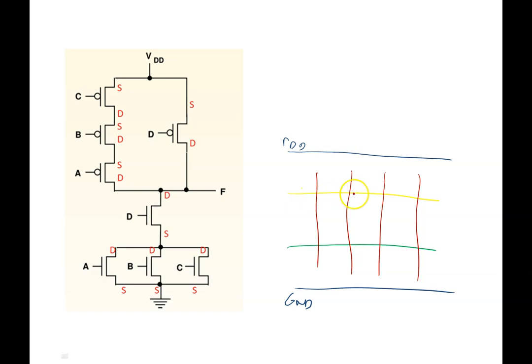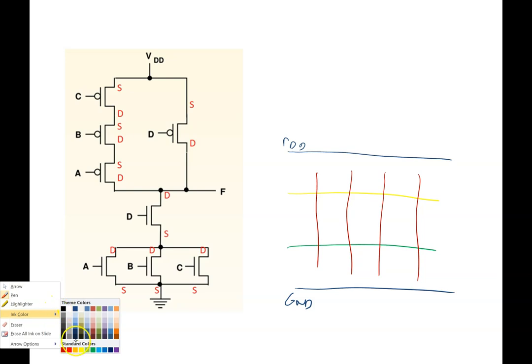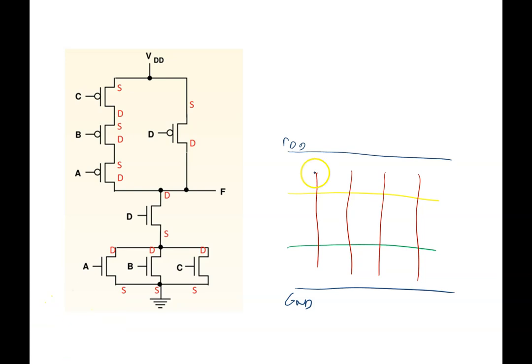So it's like creating 4 transistors here, 4 transistors there. And probably you can start with this part, which has the most serious stack. I think I'm seeing source drain, source drain, source drain. Now I got this in parallel, so that needs to be drain and source. This can easily be hooked up.